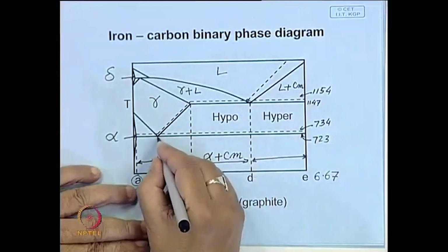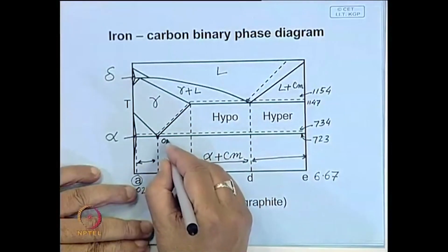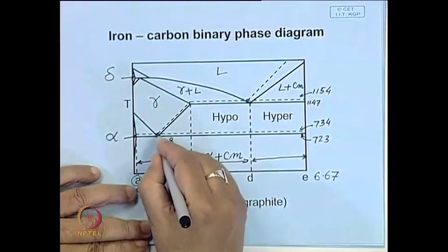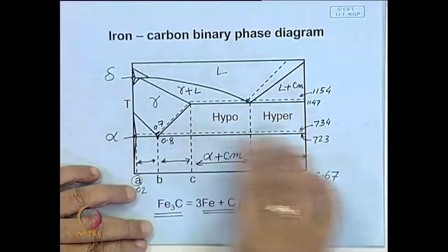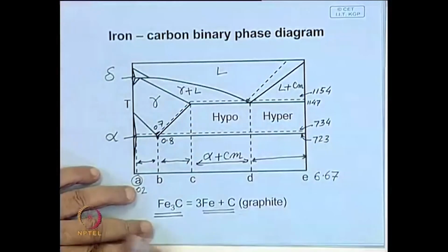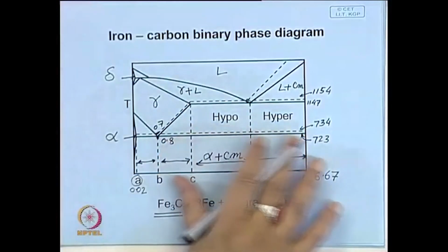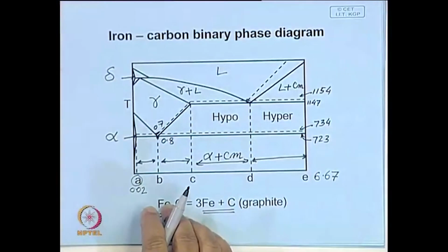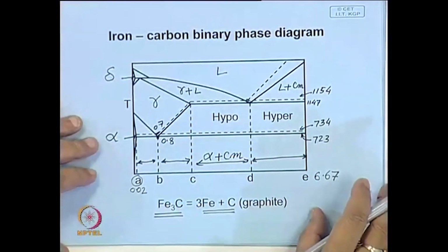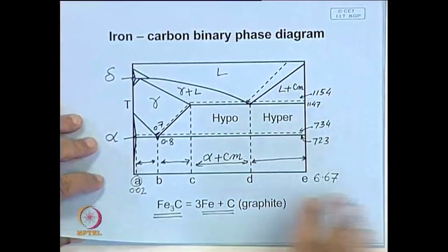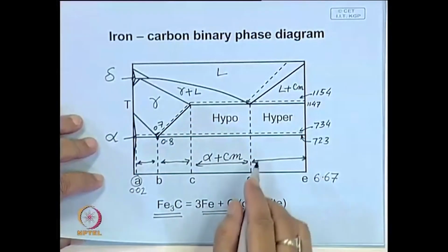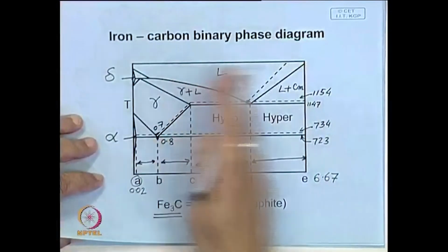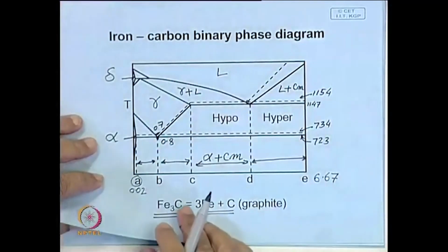So, something like that. This point is 0.8; in the graphite eutectic it is slightly to this side, 0.7. So, more or less we can use the same diagram to interpret the microstructure if graphitization does take place, and it is most prominent as the carbon content goes high.